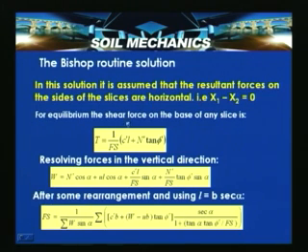So, for equilibrium, the shear force on the base of any slice can be written as T equal to 1 by Fs into C dash L plus N dash tan phi dash.